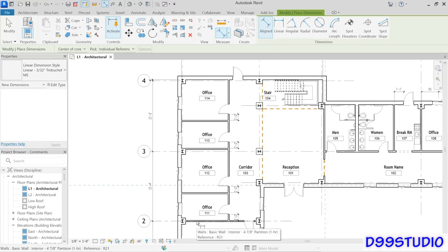And this wall down here, the center of core is where the studs are. This one, this one, this one. So all the studs are the same in those 4 walls because they're right in the center. But notice that the studs on the exterior wall are offset, right? So this is how I'm going to ensure that all of those offices are equally spaced.